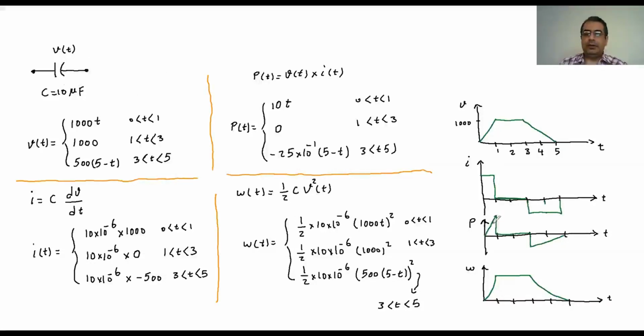So the electrical charge is going to be built up on the capacitor. You see, particularly here, the energy inside the capacitor increases. So as long as the voltage is changing, the capacitor is charging and charging and charging. As soon as the voltage becomes constant, because of this equation, if for example you have a battery that gives you a constant voltage, the current drops to zero.